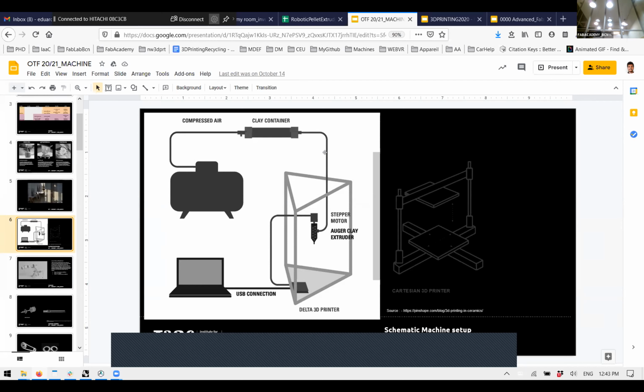For example, just before, this nozzle was 1 millimeter, and this cartridge has been here for about 2 weeks because we didn't keep it properly, so the clay is way drier than it should be. I was reaching 6 bars and it was not extruding. So I just cut it and made it double size. Right now it's 3 millimeter or more, and now it's at 6, with around 4 bars, right? Yeah, 4 bars is quite nice.